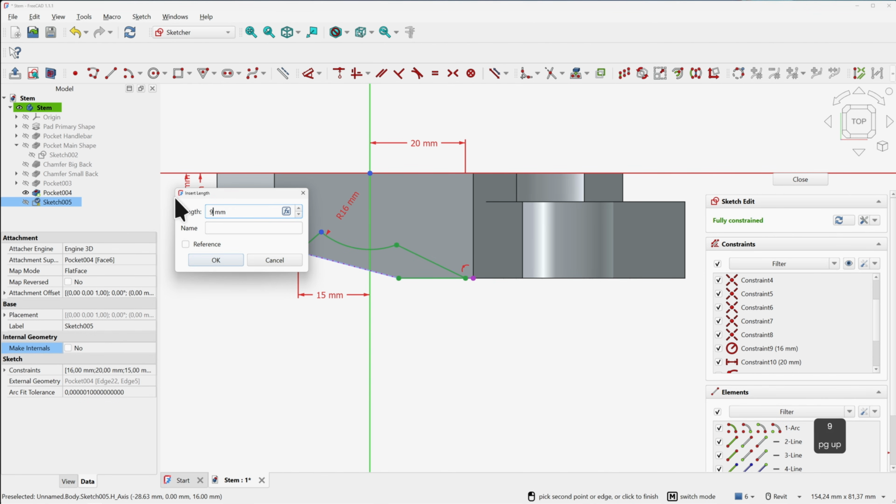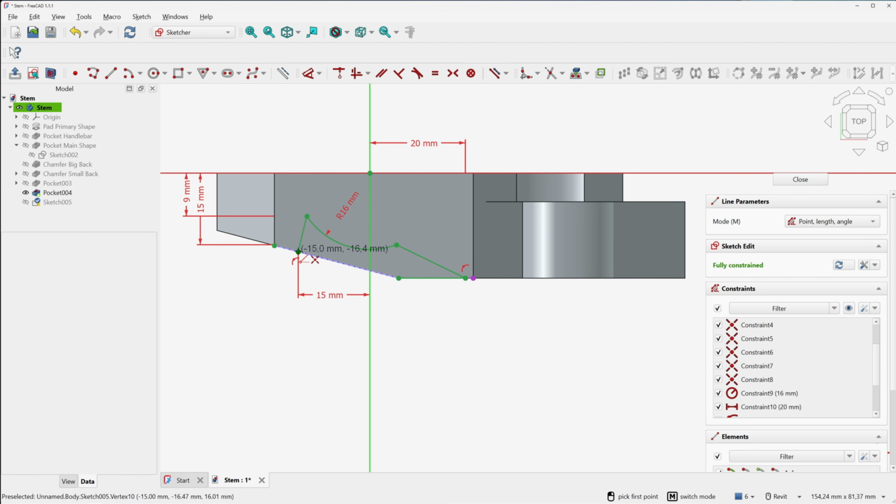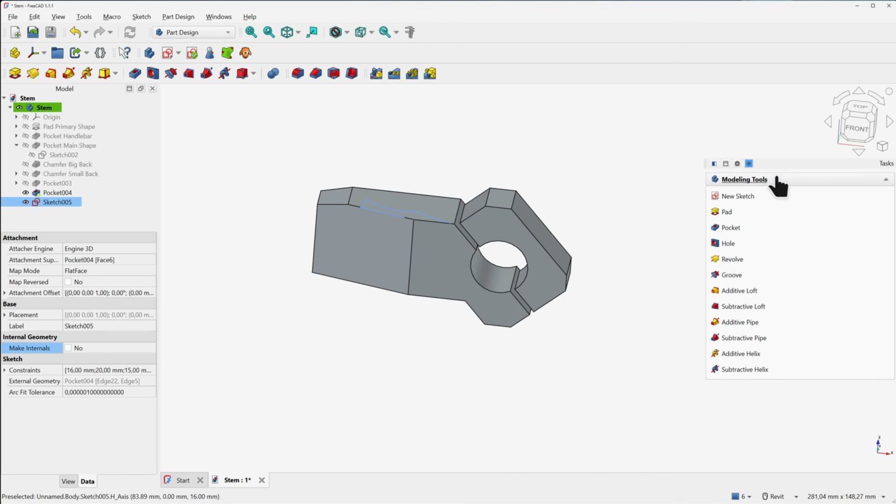The only thing left to do now is to close the contour by joining the 2 points on the construction line. To do this, we'll use the Line tool, clicking first on the left point and then on the right point. This will completely close our sketch. Great, the sketch is now finished, but it's not in the right place yet. Remember, we want the opening to start 5 mm below the surface.